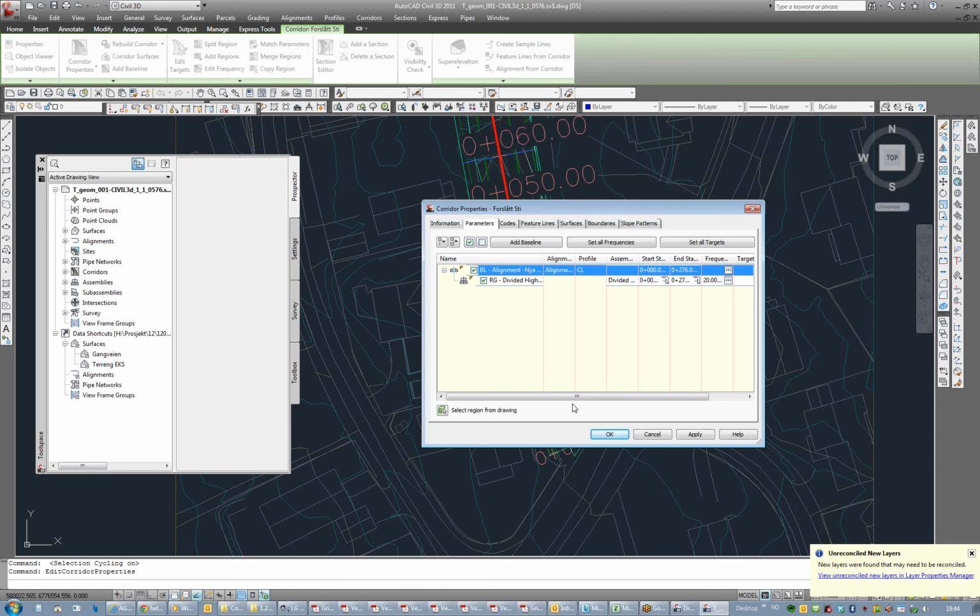Alignment, the profile. That finished ground profile is CL, right? Yeah, the red line in the profile, we call it CL. Well, for some reason it's not picking it up, because it should be up there at elevation, and it's not.